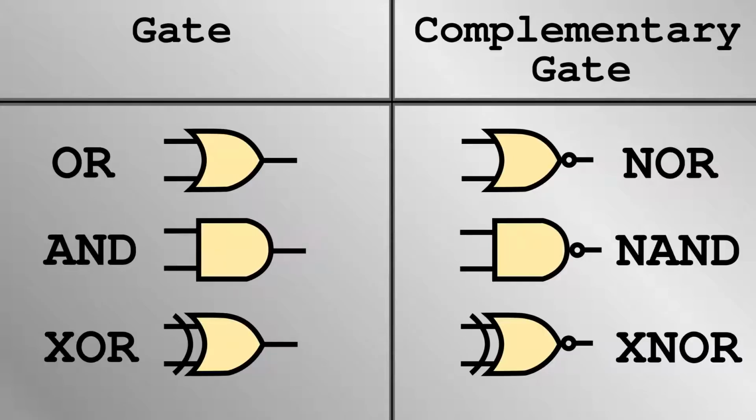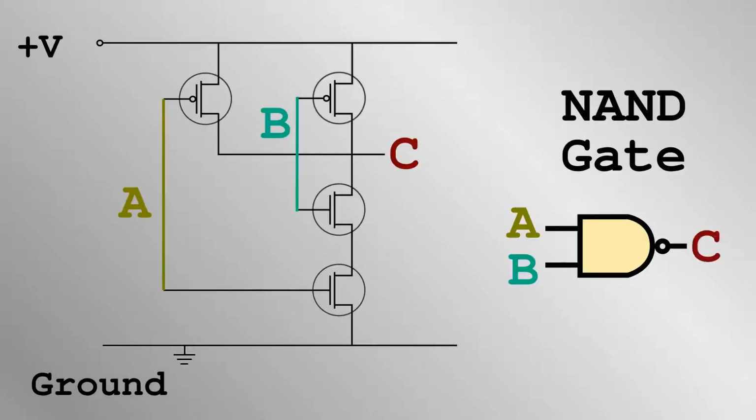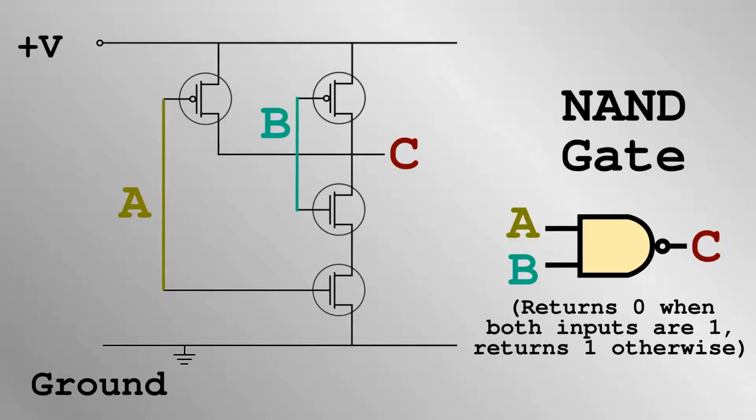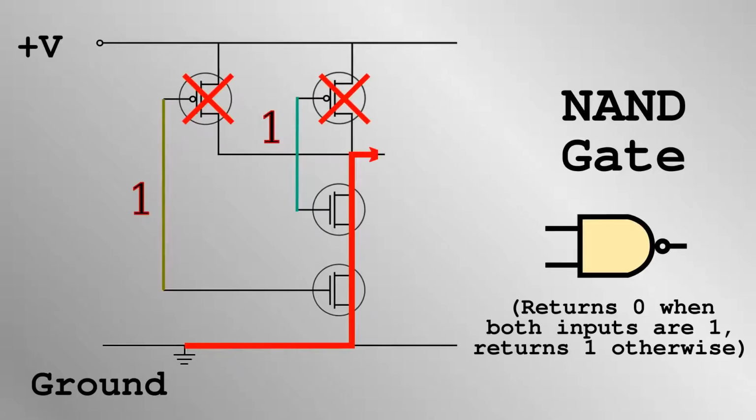For a computer, these and all other possible gates must be implemented through CMOS pairs. Connecting two pairs as follows creates a NAND gate. The N-channel and P-channel transistors still work in pairs. Only when a high voltage, or 1, is applied to both pairs of inputs do the paths to high voltage close and the path to ground opens, so a 0 is output. This is exactly the behavior of a NAND gate.